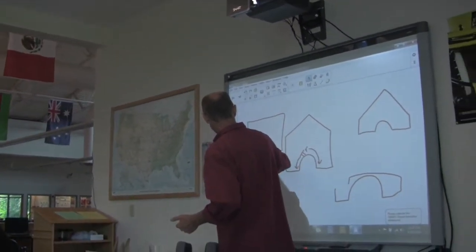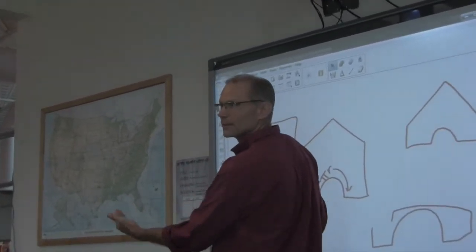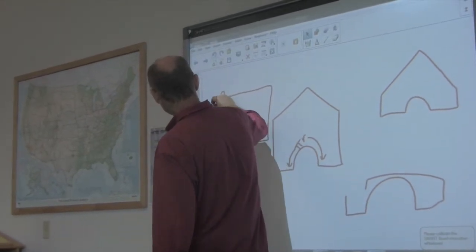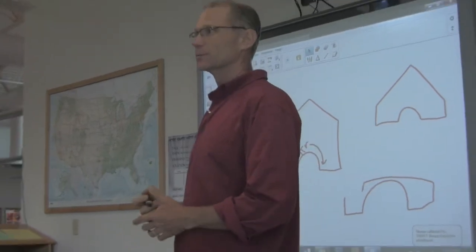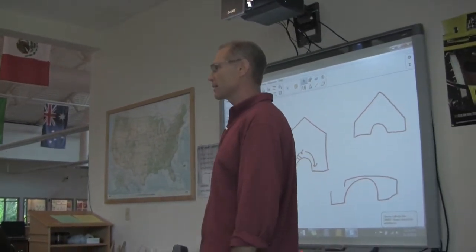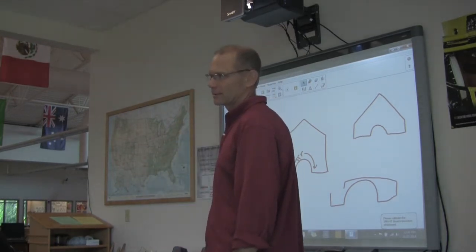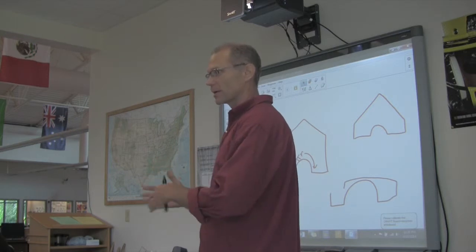out in the real world, what's to keep you from making it a parallelogram? You can't really tell by looking at it, so then they have to do the old 3, 4, 5 triangle trick, which is used commonly by builders. And so I have all these kids, they make it and the perimeter works, but it totally is like this. I'm like, all right, that's not going to work. What are you going to have to do to guarantee that the angles are right and everything is right?